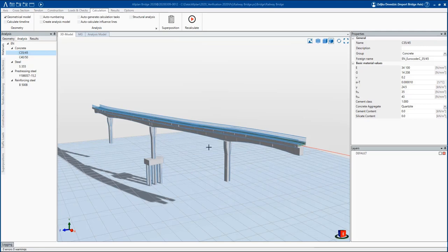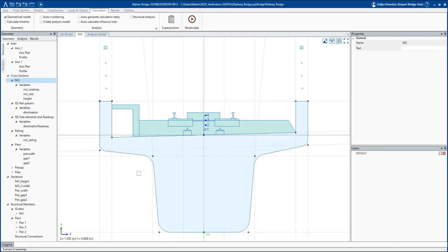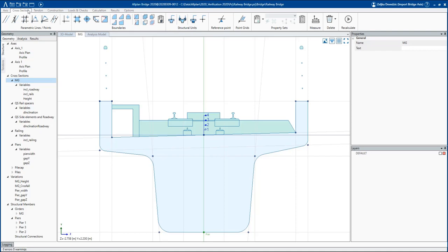The geometry of a tendon along a structural member is determined by a user-defined series of constraint points. Between these constraint points, the calculation of the tendon geometry in Allplan Bridge is performed as cubic Hermite splines. We will return to the main girder cross-section and define a point grid for positioning grid points within the cross-section. Those points will then be used as a reference for the definition of the tendons.